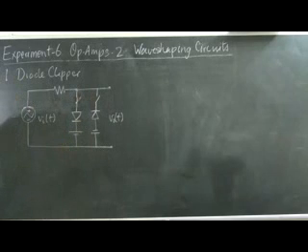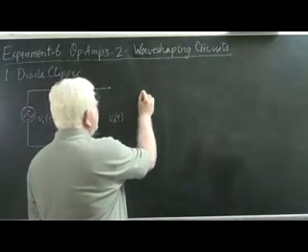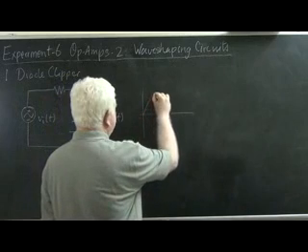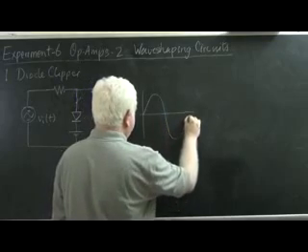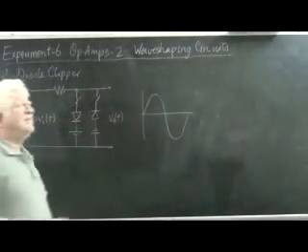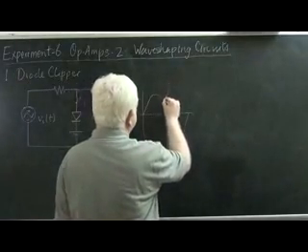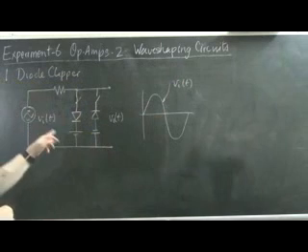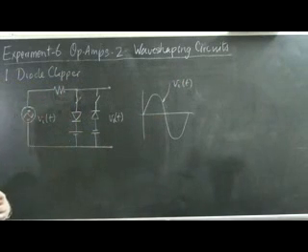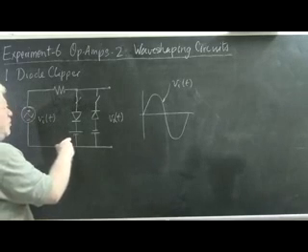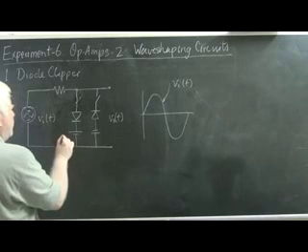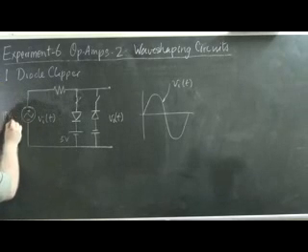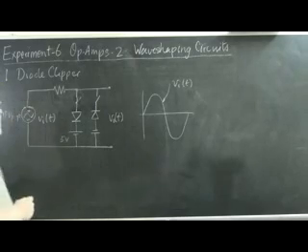So now let's understand what happens. Here's how we draw the waveforms. On the input side, we have a sinusoid. This is Vi of t. When this is applied across this diode circuit, and this battery voltage is set to something like say 5 volts, given that this is say 15 volts peak to peak, let's see what happens.